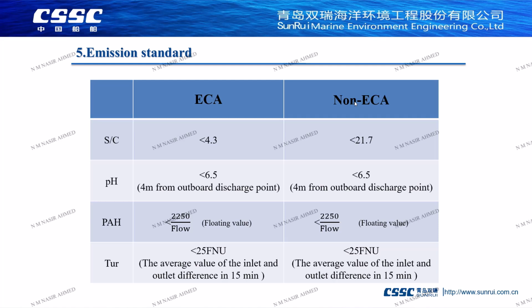This is a variable number for pH, as required by law. It is calculated from the flow of seawater sprayed at the current running time and the total power of the main generator. So, the limit value of pH during operation is a variable.